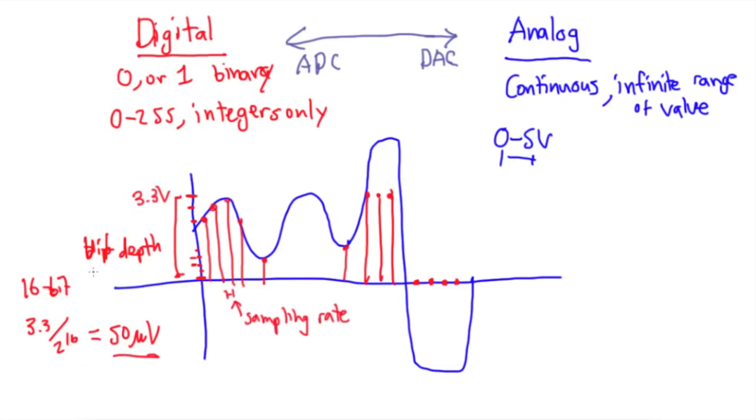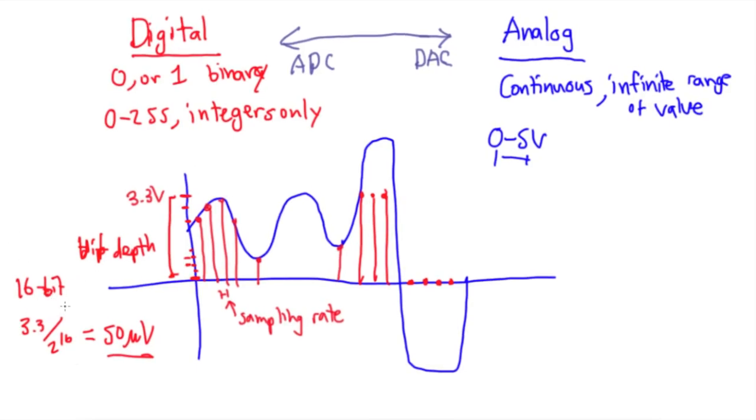And as another instance, the cell membrane potential is typically 60 millivolts, so you can actually pick that up. So these are just a few things to keep in mind, and that's also partly another reason why we picked the KL25Z, because of the 16-bit ADC, which is useful for a lot of biomedical applications. And with that is also the idea of the digital to analog converter. It works a lot like this, but it goes in the reverse direction, where it converts some sort of digital signal to an analog signal.